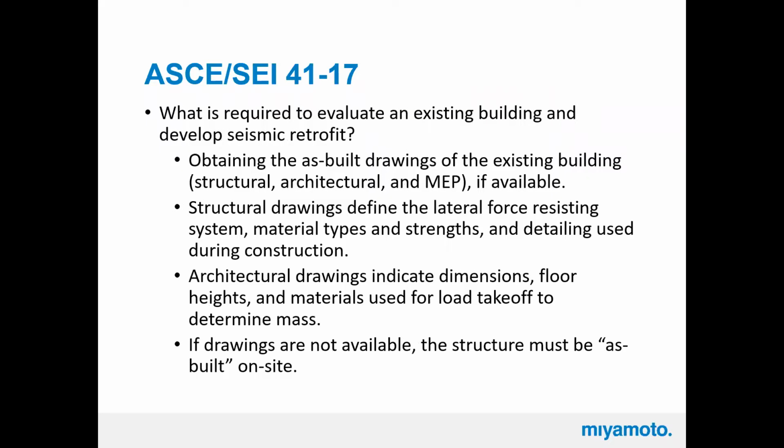After we've done our Tier 1, it'll allow us to much more deeply evaluate the characteristics of a building that didn't pass the Tier 1 screening. And then Tier 3 is a full building analysis. It can lead to design of either the full building or the full building with new elements and new features put in. So there's my ASCE 41 lesson.